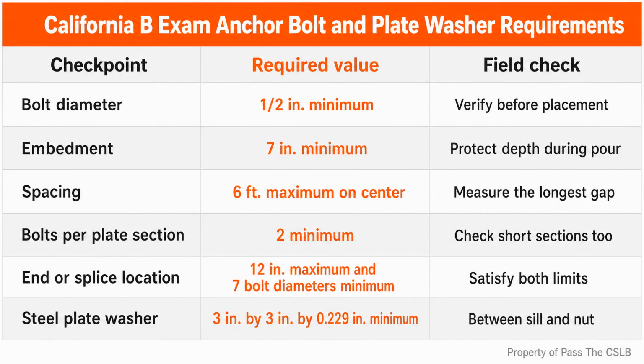Suppose a crew drives short rebar stakes beside a footing form and leaves the ends exposed because they rise only a foot or two above grade. The hazard is still at the height where a worker can fall onto it. The correct field response is to guard the projection with approved impalement protection and keep the walking and material handling area controlled. Shorter does not mean harmless.